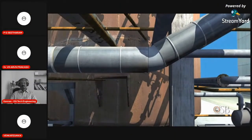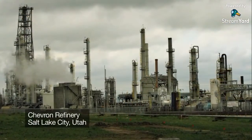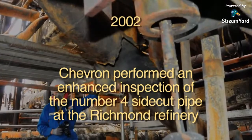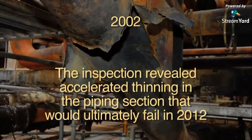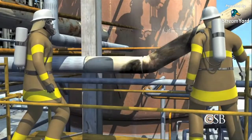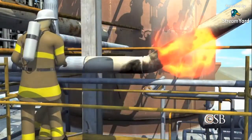The CSB learned that sulfidation corrosion had caused a major failure at Chevron's refinery in Salt Lake City, Utah in 2002. Chevron then performed an enhanced inspection of the number 4 side-cut pipe at the Richmond refinery. It revealed accelerated thinning in the piping section that would ultimately fail in 2012. Replacement was recommended, but this did not occur, and the section of piping was never inspected again.